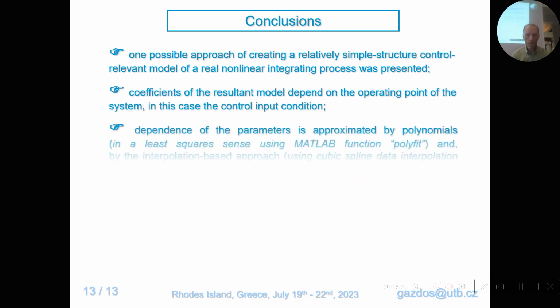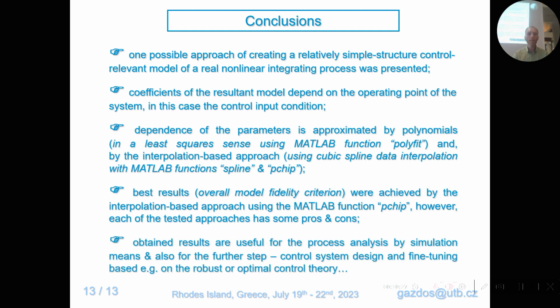So finally, we have just tried one possible approach of creating a relatively simple structure and control relevant model of a real nonlinear integrating process. As a result, we have a linear model, but the coefficients of this model depend on the operating point of the system, in this case on the condition of the controlling valve, and the dependence was modeled and approximated by several methods.